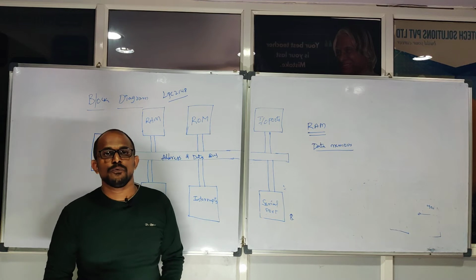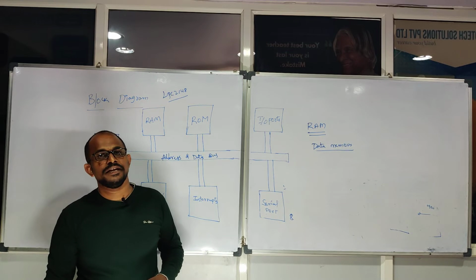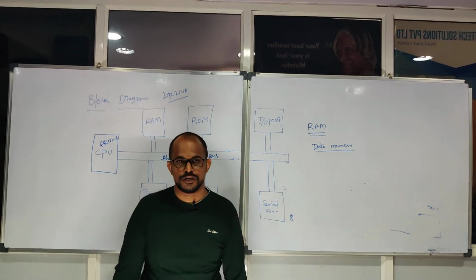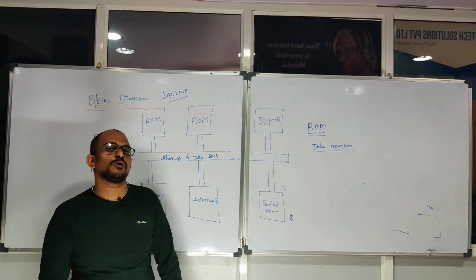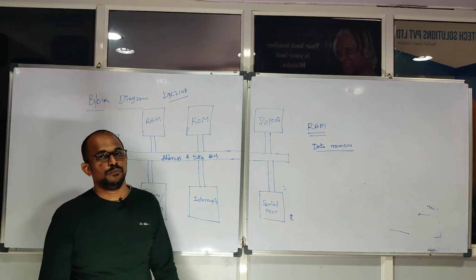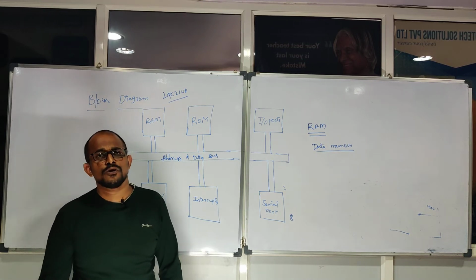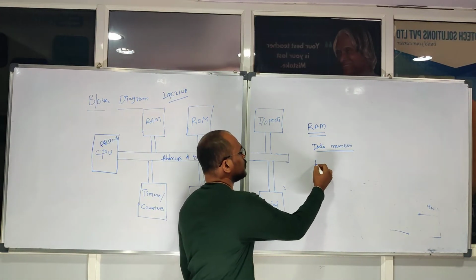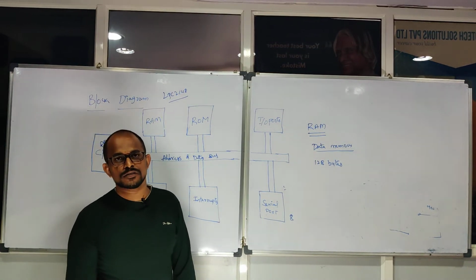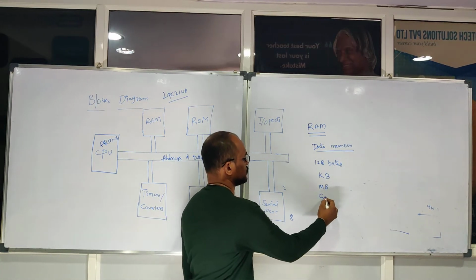Again, RAM has one more property. Whenever you switch off your microcontroller, it will lose the complete data. So that is the only reason it is called temporary storage. It is used only for processing the entire code or your applications while the CPU is running. Your RAM changes from controller to controller, but in basic microcontrollers you may find it in bytes. Moving on to 32-bit category controllers, you may get KBs, MBs and GBs.